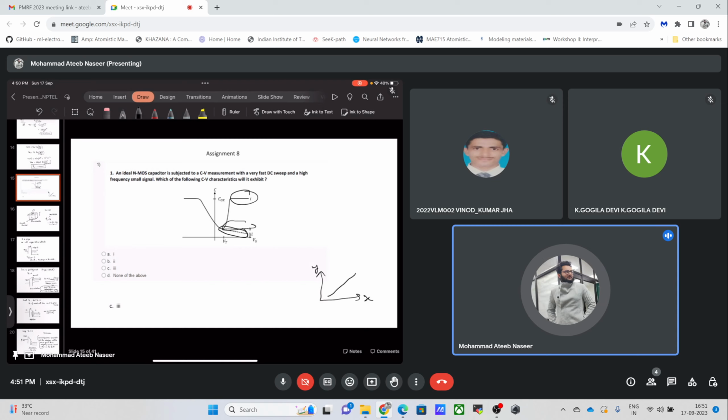Now, in the accumulation or depletion region, since it mostly involves majority carriers, the concentration inside this structure will change rapidly in those cases. But for the inversion case, as the ramping changes from depletion, as we are transitioning from depletion to the inversion region, there will not be a significant number of the carriers that we will require for inversion.